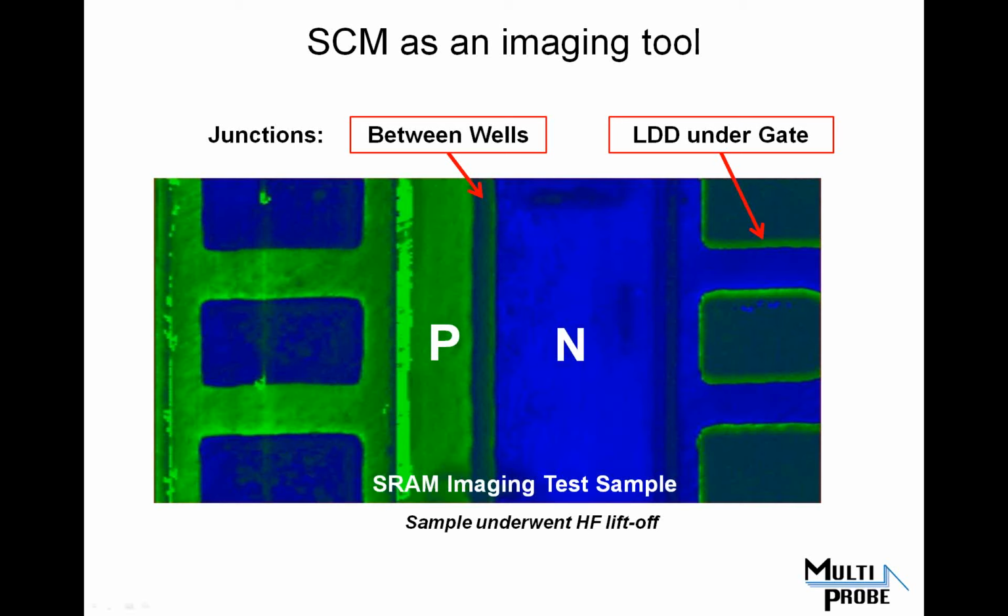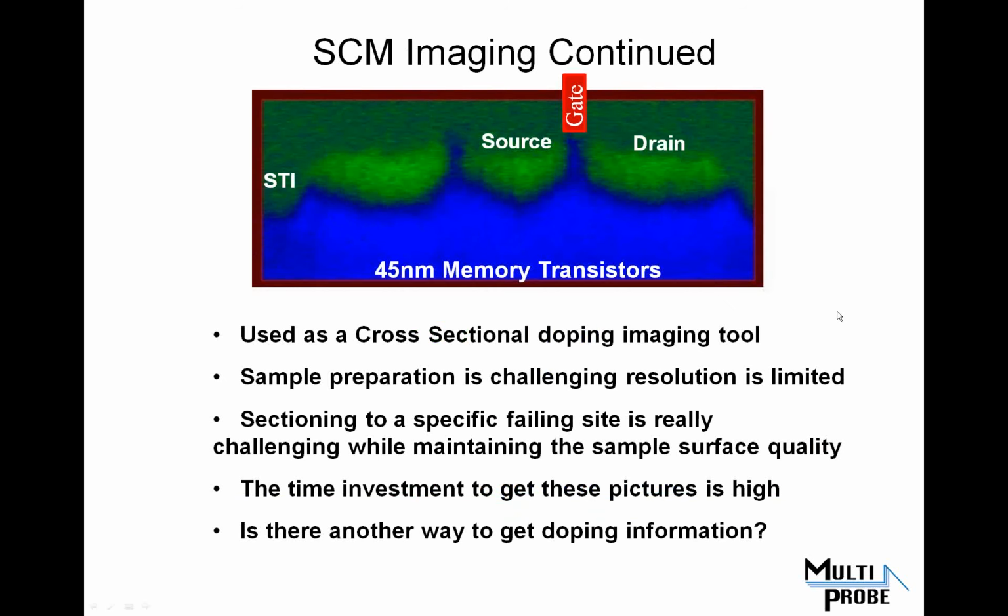It turns out you can also still look at some transistors. And so this is a 45 nanometer transistor, and I've put in a little structure here to represent the gate, which isn't visible in the capacitance measurement because, of course, well, I think the doping's so high that it doesn't see it anymore so much, and its connection isn't all that good. But you can see the source and drain implants. That would be the light green region, and you can see the junction between them. And since that gate is 45 nanometers, this is a much smaller structure than the previous one. And so the image will look a little bit more blurry. You can also begin to see the resolution limits in imaging.